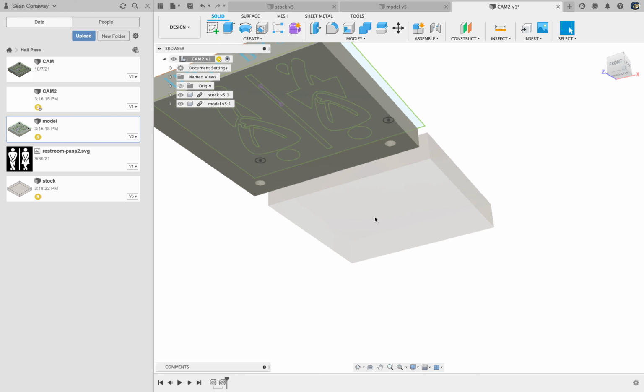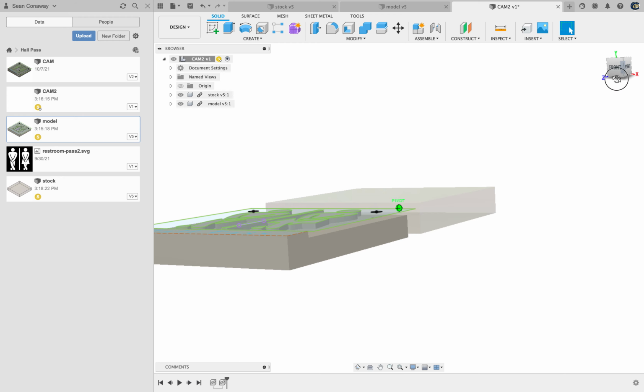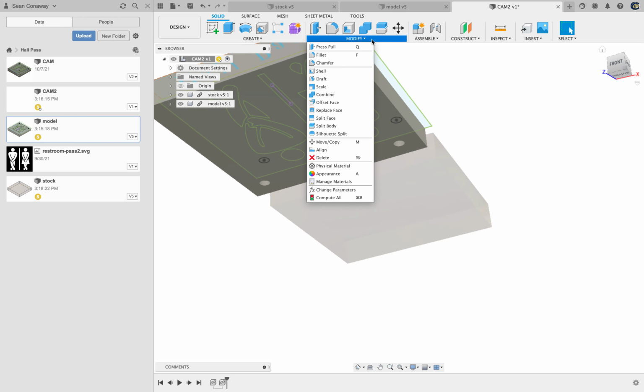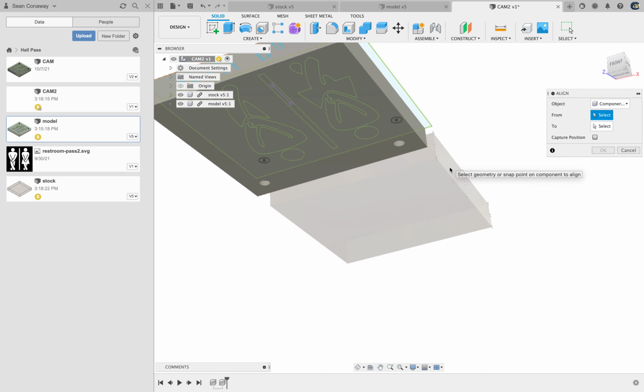What did I do wrong here? All right. We'll figure that out. Oh, yeah, I see what I did wrong. I'm going to go back in there. Here's a learning moment for us, guys. Okay. I don't think I had components selected before. I think I had bodies selected, right? And these two things, if you look up here, you could see that these things are components. I can tell because it's a cube, right? But over here, I think I had bodies. So I'll have to go back and watch a video and make sure what I did, but I need to make sure that I have components selected.